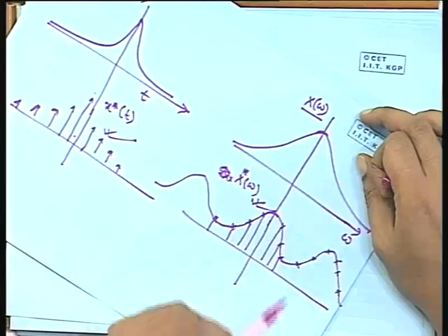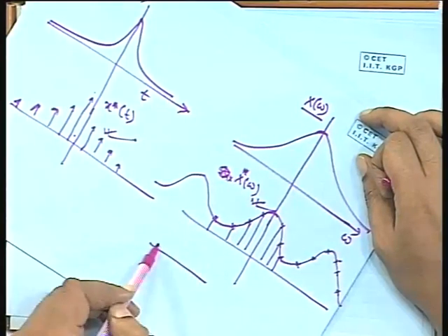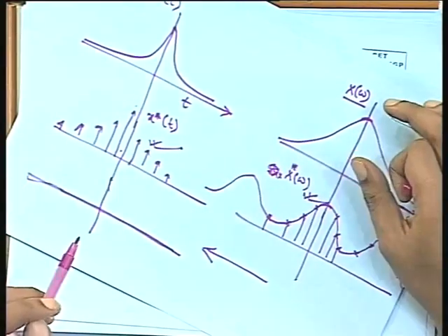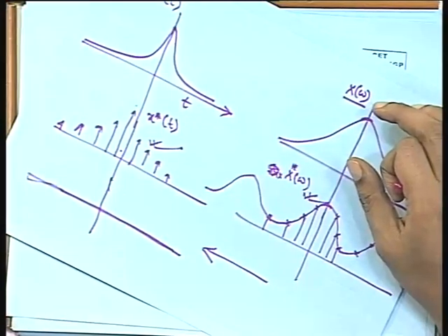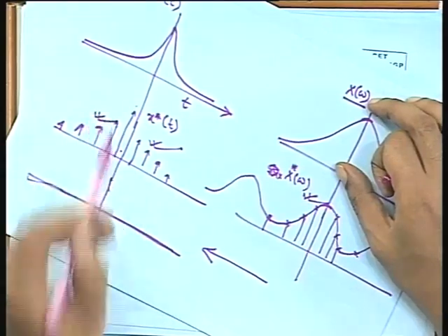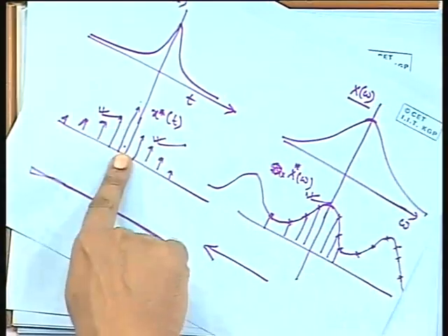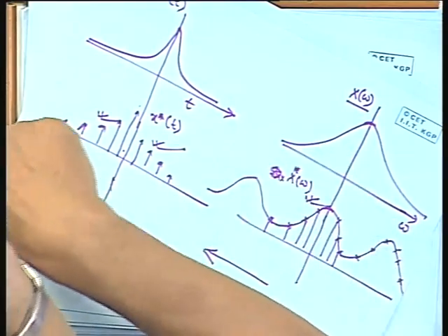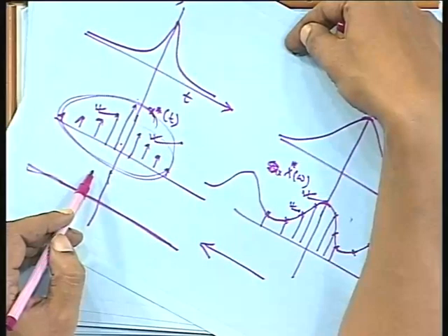Now from these sampled values, by what is known as an inverse DFT, I can go back to a sample time sequence, and that sample time sequence will be a periodic version of this. So if you sample in one domain, you get a periodicity in the other domain. If you sample in the time domain, you get a periodic thing in the frequency domain. Now if you sample this thing, you will get a periodic sample time function, because this was the original time function. So if you sample this, you will get this time function periodic, right?